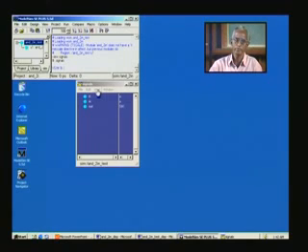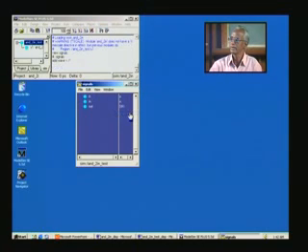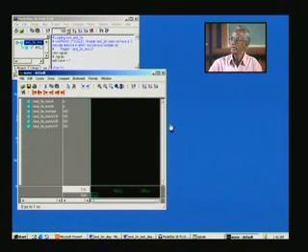This may be difficult for you to read, yet just follow my words. I am going to click on view here, and it has a few options: wave, list, log, filter and so on. In this, go to wave and then take your cursor down. We want all the signals in the design, including the test bench, not only your design but also the test bench. So if you use this one option, you will get all those. I am just clicking on signals in design. Immediately you see a waveform window opened.